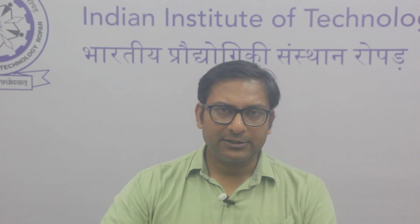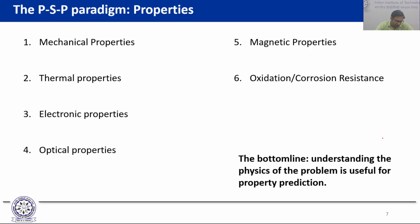And for that, let us look a little bit into material properties. When we look at material properties, you can have many different classes of properties. I'm just listing a few common ones over here. For instance, when you look at mechanical properties, you might be interested in predicting something like the yield strength, or the hardness values, or the Young's modulus, whatever it is. You will find that some of these properties are very composition dependent, whereas quite a few properties depend heavily on the microstructure. The hardness or yield strength, for example, is quite sensitive to the microstructure.